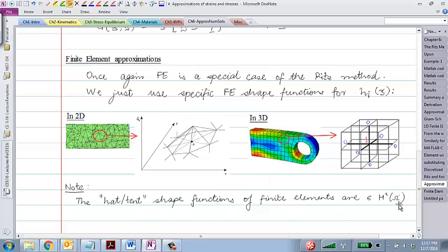And now for the other part, when I was telling you, let's say this is a plane strain or a plane stress problem with part of the edge fixed in different ways, can you think of a way that you would be able to enforce that condition here? Let's say this part of the edge, we want it to be fixed against movement in the x direction.